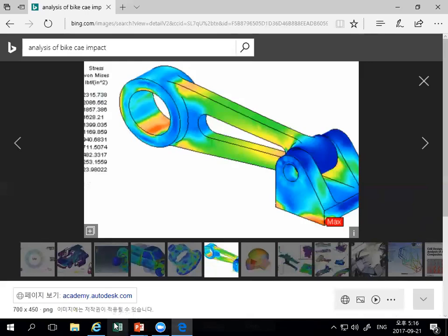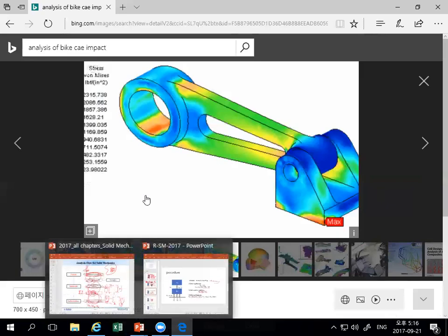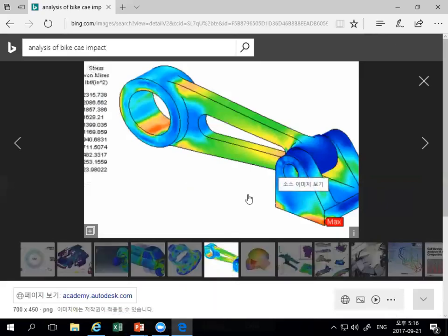So we can see the sigma X, six components, sigma XX, inside the body or surface, and strain. How do they control this distribution? Three rules. One is the equilibrium, and stress-strain material property relation, and strain-displacement. So that is the one, and we cannot just solve by hand. Well, a spring is easy, we can solve, but this is some link system.